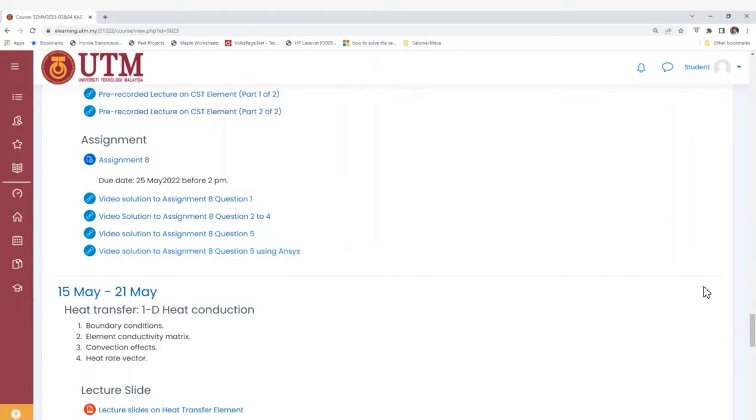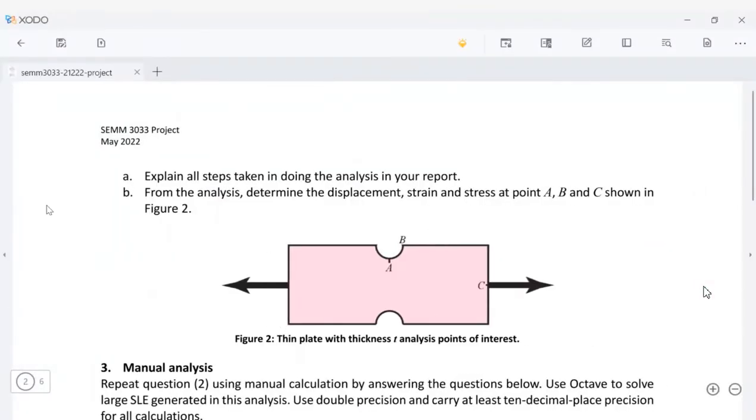Use a minimum of 12 and, by identifying all boundary conditions, do a finite element analysis on the quarter model of the plate. Quarter model means you cut it here and you cut it here. Then you have a quarter model, not the whole model, because the whole model will consume your PC time. So what you want to do is to reduce the computation.